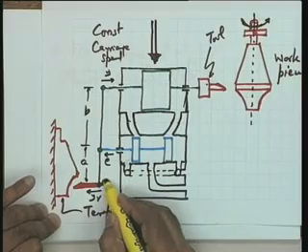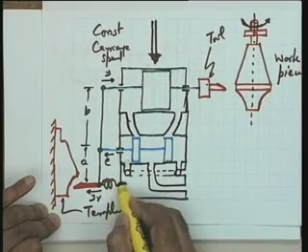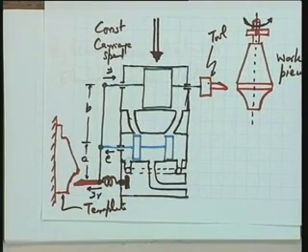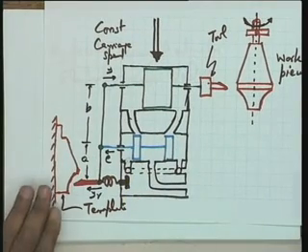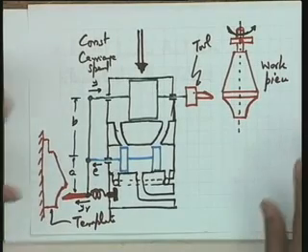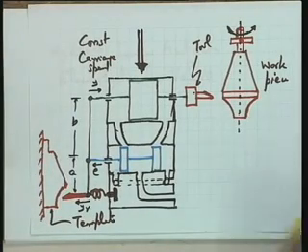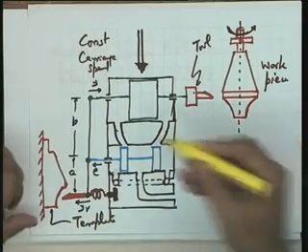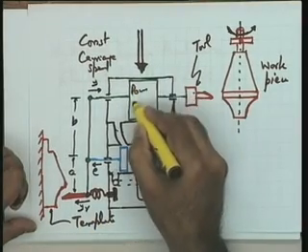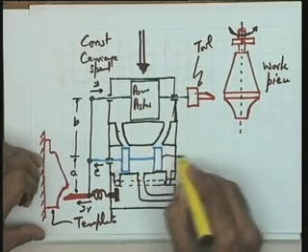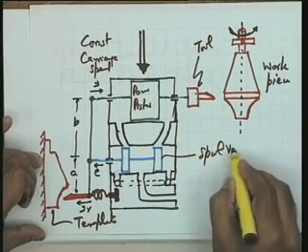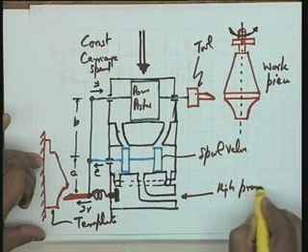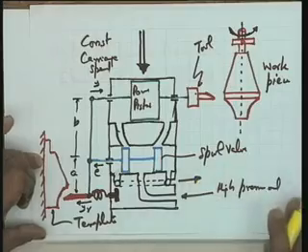I can say that there is a spring over here whose tension can be suitably controlled. This arrangement is there. Now, let us see how this system works. Assume that in this particular case YR is set, but before I give you this description, I hope you will recall this is your power piston here. Here is a spool valve. This is your high pressure oil, and this is going to drain to the reservoir.